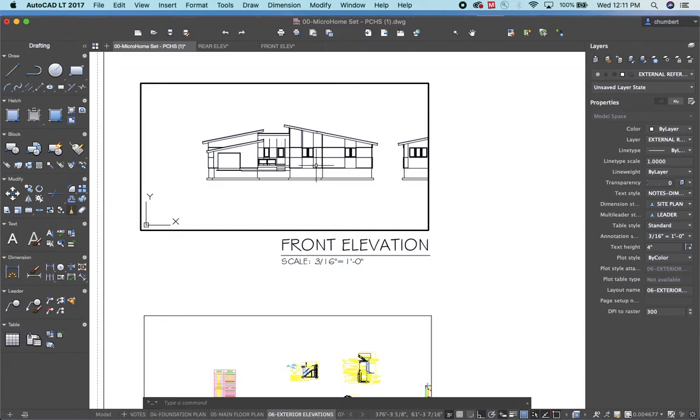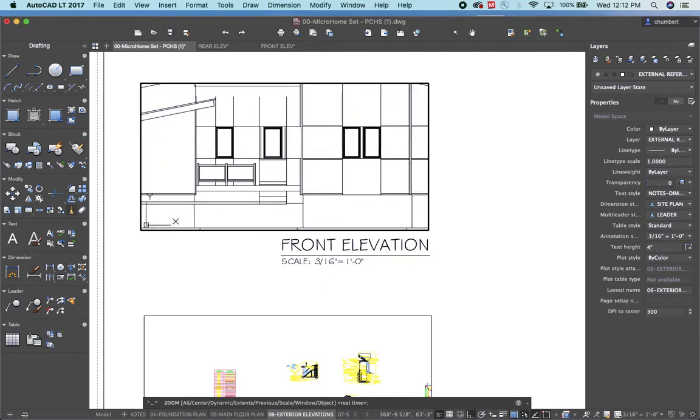So to make this zoom correct now, you have to type in Z, enter. Then where it tells you there, it says enter a scale factor, and then you type XP after it. So I'm going to go 1/64 XP, enter, and it fixes the scale.